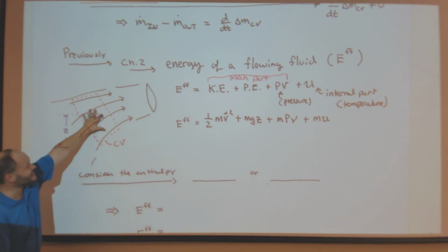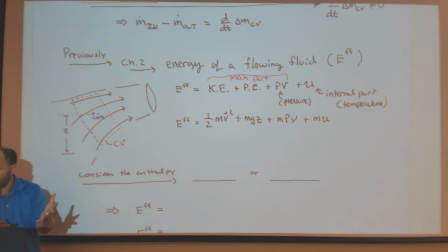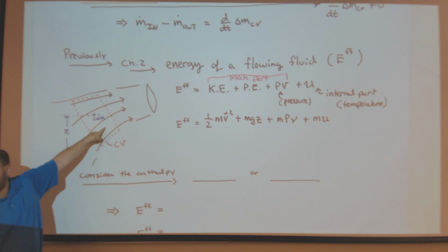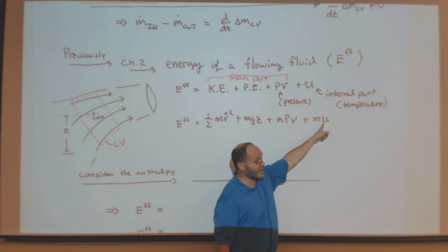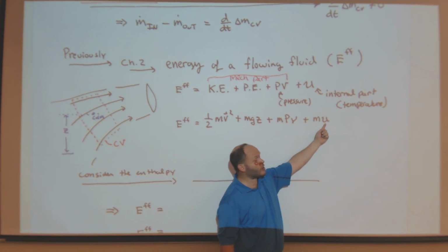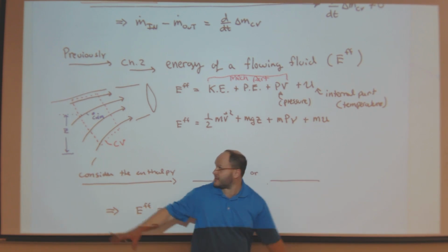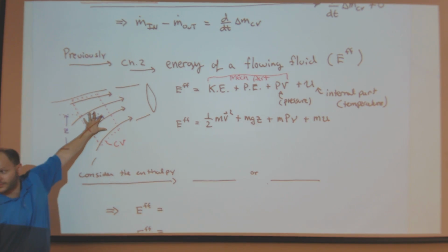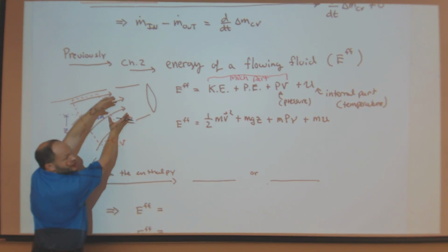This thing has a temperature. I drew a boundary, I had defined a control volume. In order for me to describe the state of this, I need to know 2 independent intensive things. Once I define the temperature, and I say it's, say, water, I can go look up what this is. I know its mass based on the size of the control volume, and I got its total energy. Now this control volume could be changing.